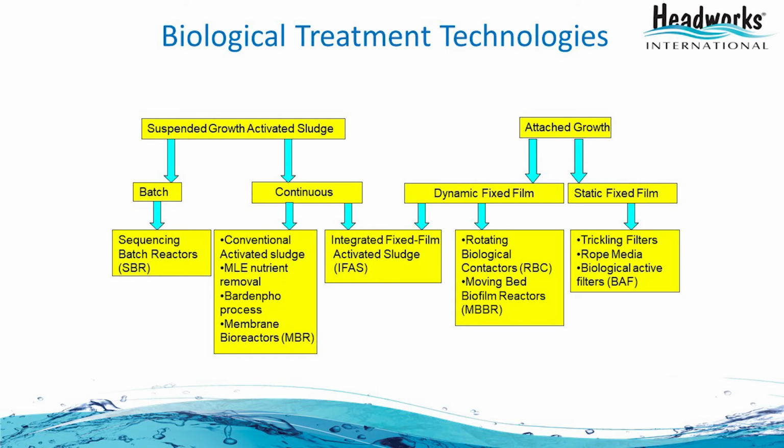And in that wastewater treatment tank or reactor, there is a population of microorganisms that conduct the reactions to remove BOD by oxidation and ammonia also by oxidation to nitrate. Attached growth processes, as opposed to suspended growth, the microorganisms are attached as films on surfaces of media, and these media are made up of synthetic materials like polypropylene, polyurethane, or even rocks. So depending upon the type of reactor, there are different types of media that are used in the industry.